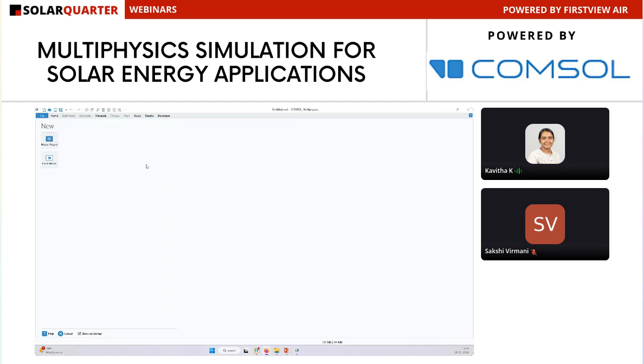So when you open the COMSOL session for the first time, this is the window that you will be taken into. We have two ways to enter the desktop interface. You can choose model wizard or blank model. Model wizard is the recommended approach where you will get to know the different types of physics that can be solved, what physics interfaces you have to choose, and what types of studies are available for the physics interfaces. So this will be a guided approach. The recommended approach is the model wizard. Let me choose the model wizard.